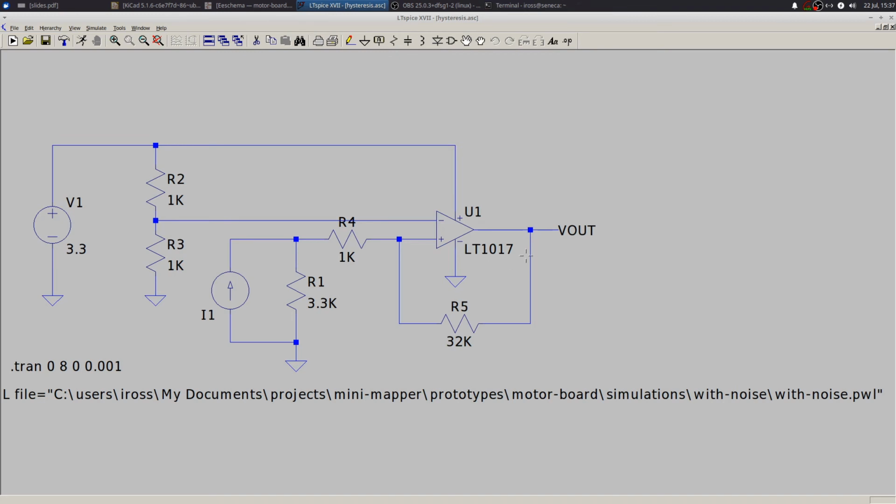So the easiest way to think about what's happening here is to think about what the situation is if V out is 0. If V out is 0, then this point is grounded. This voltage is the signal based on the phototransistor current. But because of the voltage divider made by these two resistors, the voltage that we're applying here is only 32 over 33 times the voltage here.